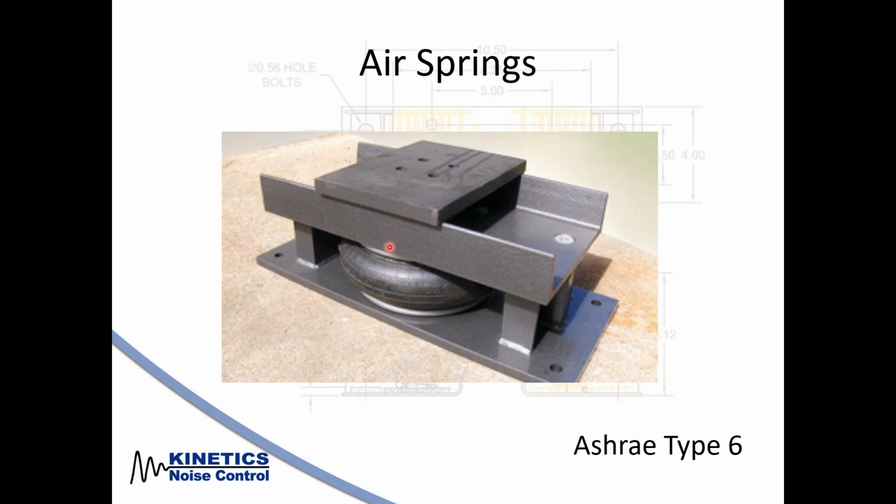Most times you're going to want to go with springs though, because an airbag of course does need air. That air comes from an air compressor. That air compressor is noisy, it vibrates itself. So now we've got another element in the system that needs isolated. They're very expensive because they need a control panel to control them, as they're self-leveling.